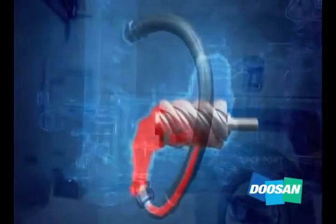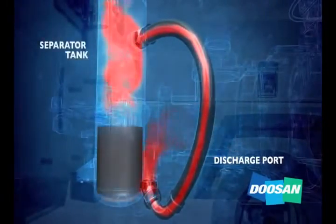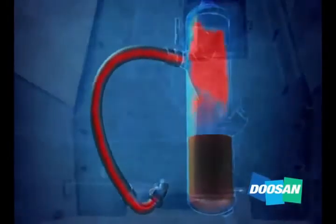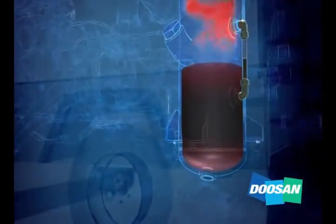The air, now mixed with oil, exits the air end through a discharge port and is piped to a separator tank. Here the separator will remove some of the oil from the air and let it accumulate in the pressurized tank. The tank acts as a reservoir as well as an oil service and fill point for maintenance. A sight gauge mounted on the tank's side allows an operator to quickly check the oil level.